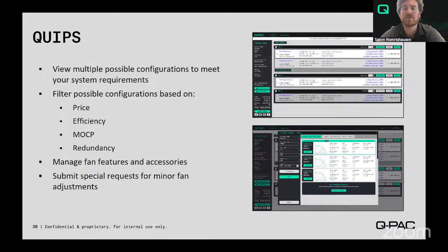When you see a percentage value for redundancy or resiliency, that's really kind of code for: if you have 100% redundancy, resiliency, or higher, that's going to be the same as having N-1 redundancy with the number of ECM plug fans on the wall. So if you lose one ECM plug fan with 100% or N-1 redundancy, the other ones would be able to ramp up to compensate for that and get you to that total performance you selected the product at.